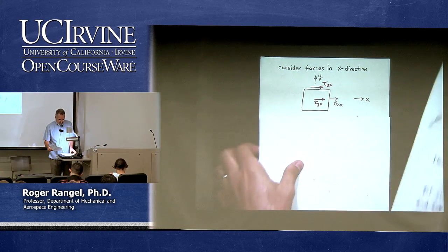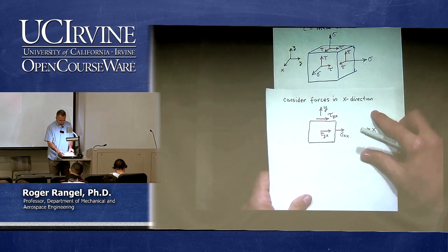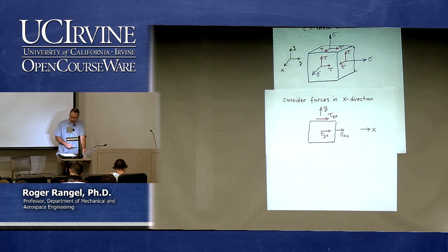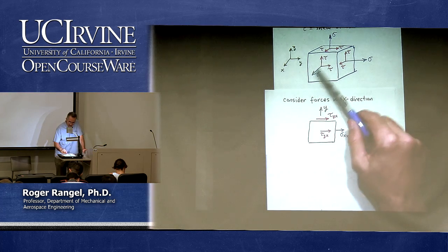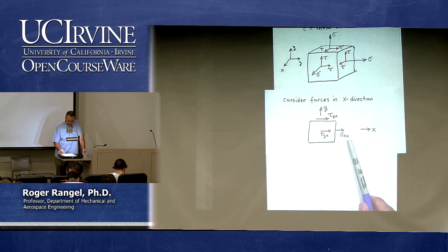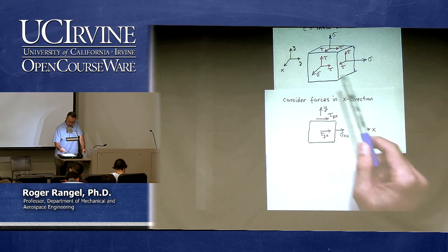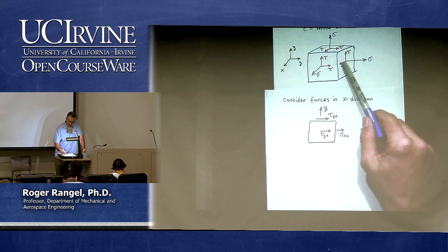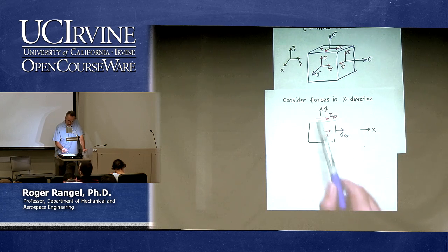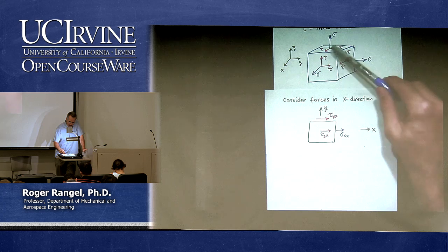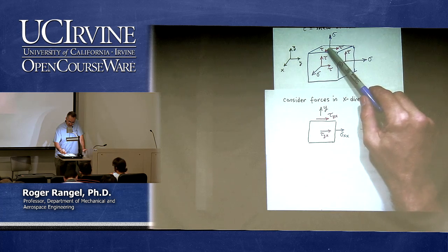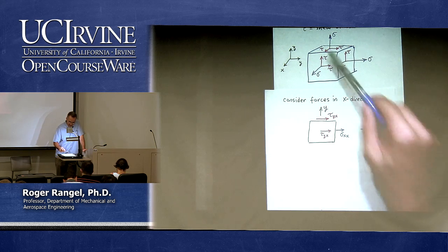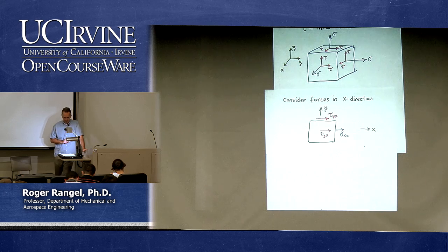Maybe I'll keep this 3D figure here. So I'm just taking the x direction. So I'm taking this sigma right here, which is this sigma xx. I'm taking this tau that I told you, which is tau yx, and in this drawing it appears on top. And then this one that was on top here, which is a tau zx, is actually now here.